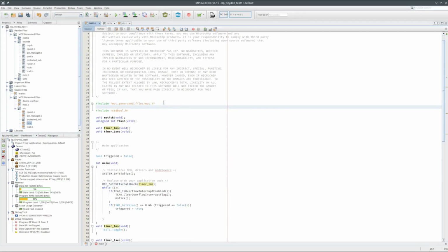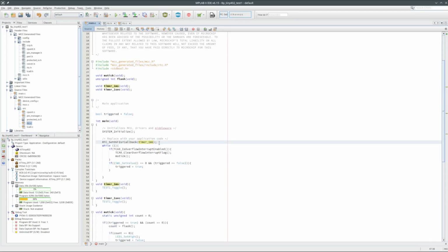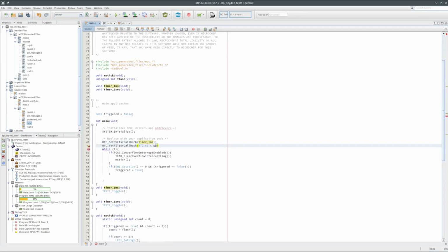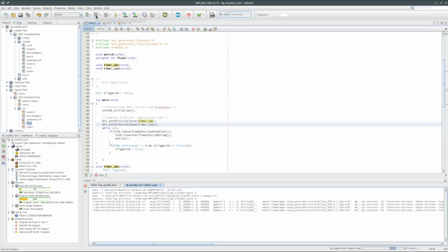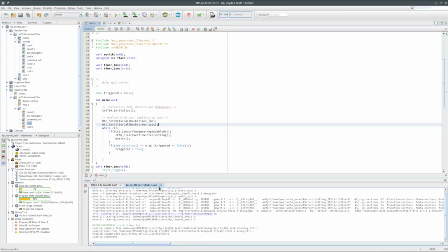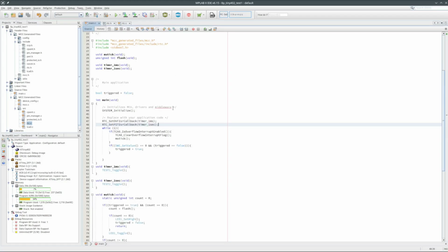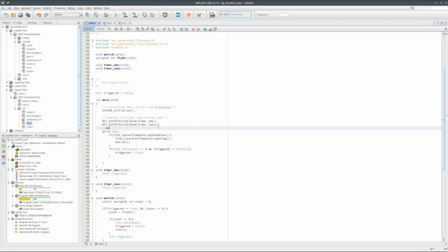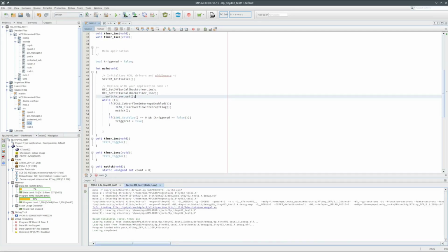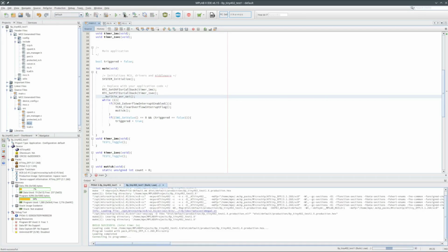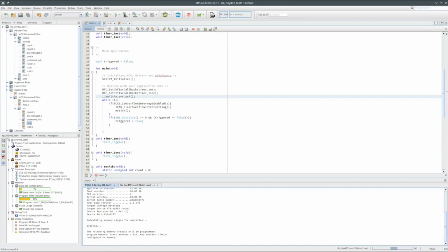Almost forgot to include the rtc.h header file. Then I'll add the period interrupt timer callback. And then compile it, and no errors. But I've still got to turn on global interrupts for it to work. I'll have to look that up. Okay, had to hit the XC8 user's guide for the AVR built-in functions list. I don't think I ever would have guessed that one. There's supposed to be a macro called EI, but I'm going to use the full built-in function name.